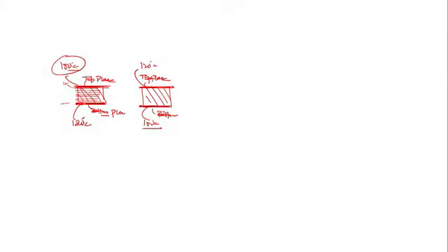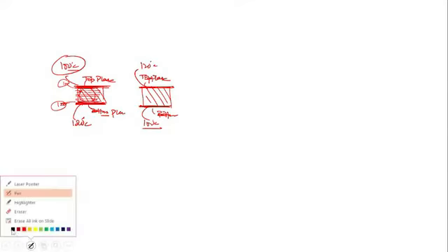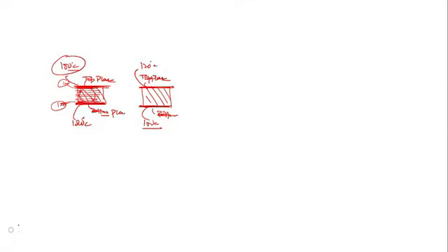The fluid layer just on the surface of the bottom plate will be at 120 and the layer at the top plate will be at 100. That causes a difference in temperature and that causes a difference in density. The high temperature fluid will have low density and will try to rise up, and the low temperature fluid will have high density and will come down. That causes the bulk motion in the fluid. Yes or no?